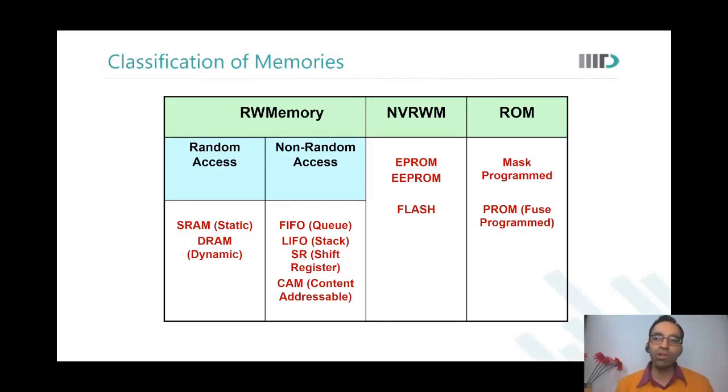But if you need more words, then FIFOs are more area efficient. What's the difference between FIFO and shift register? FIFO is based on an SRAM kind of architecture. Shift registers are based on flip-flops. Okay, sir, that's clear now.